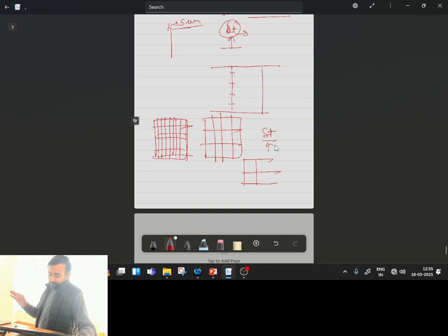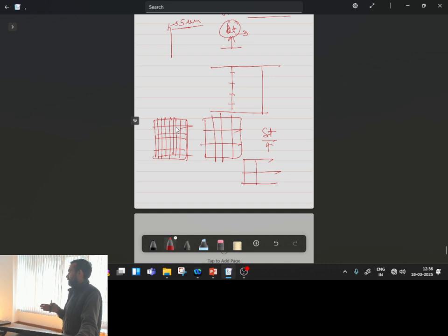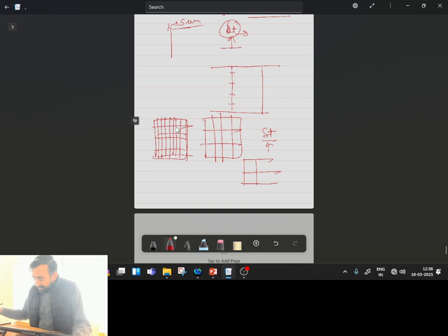And at the same point of time, we always have to keep in mind that whenever we are partitioning or smoothing, making fine our subframes, each subframe should contain at least 10 to 15 particles. We cannot go below that, because if we go below that, we will not be able to make a good estimate of the correlation between the two subframes. Is this point clear?